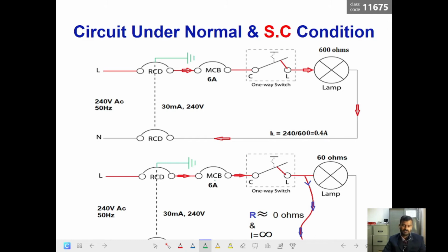It's a thumb rule for the MCB or fuse, and then the conductors have a rating above that, and the load would be the last one. So this is how they design these wirings. Compared to the conductor and load, we must have the lower current rating for the MCB.